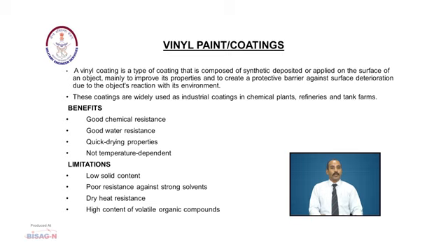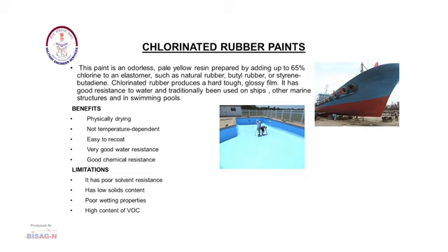Benefits: good chemical resistance, good water resistance, quick drying property and not so temperature dependent. Limitations: low solid content, poor resistance against strong solvent, dry heat resistance up to approximately 80 degrees, high content of volatile organic compound.